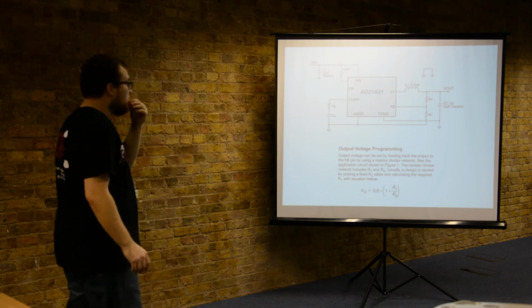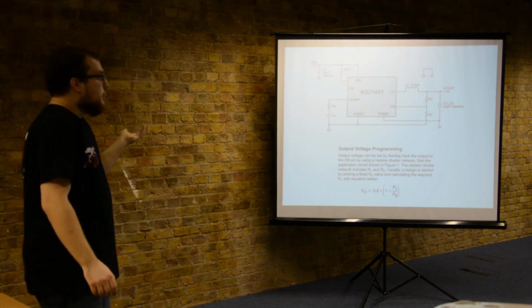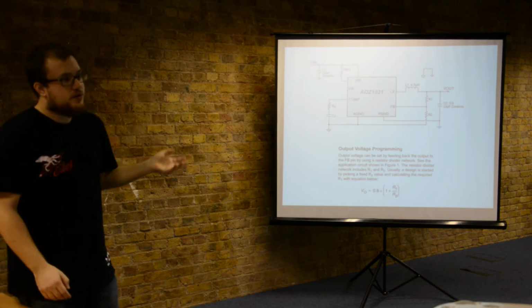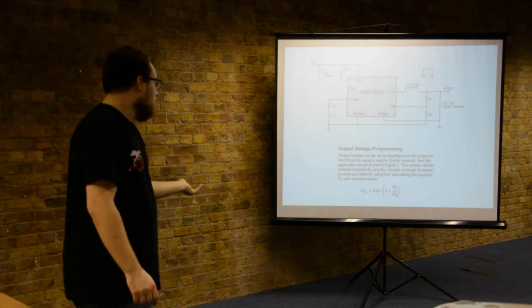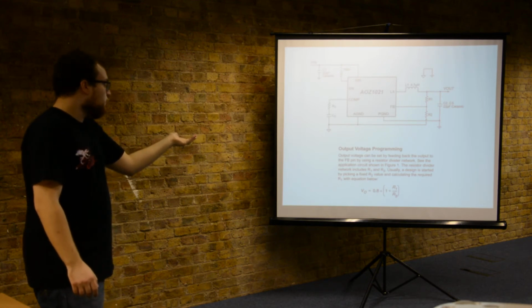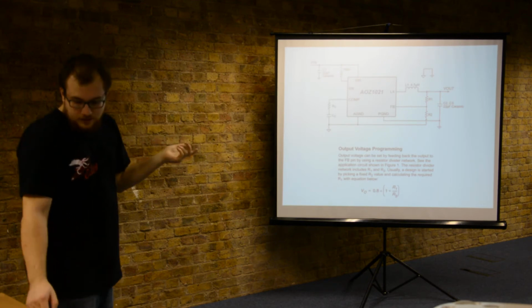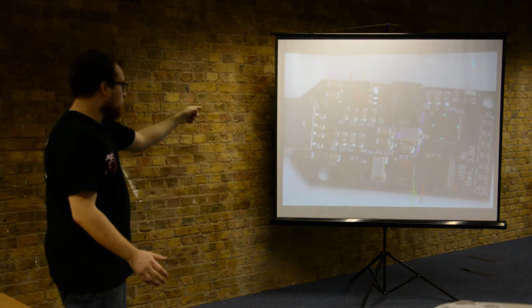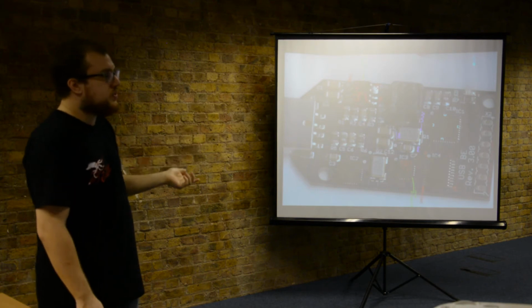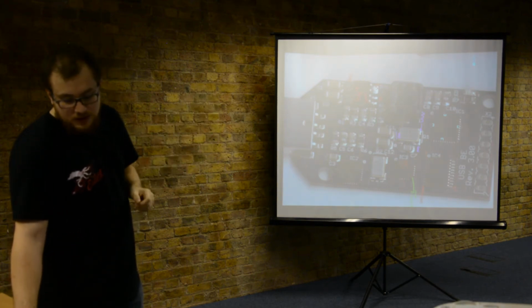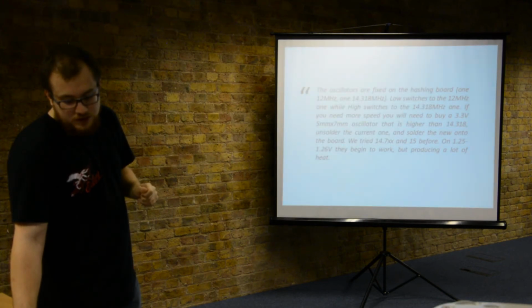So this is a fairly simple arrangement. By changing the ratio of R1 and R2, you can increase or decrease the voltage going into the ASIC chip. And that is the formula to drive it. If you look at the circuit over here, luckily these R1 and R2 values actually correspond with the data sheet. So if you just replace R1 with something else, you can get a different voltage value at your ASIC.